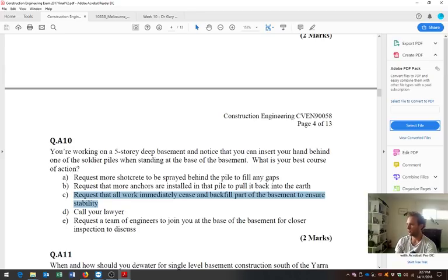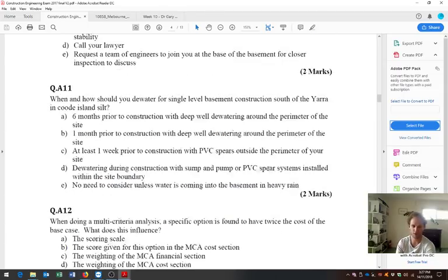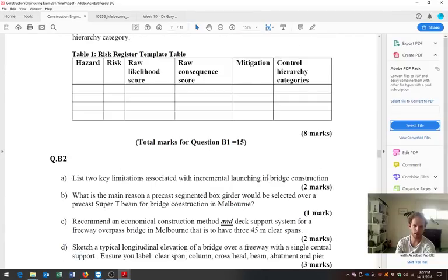2017 B2C. 3 spans, 45 metres. So plate girder is pretty good, but the best solution here is... Actually, let me double check this question before I get too far ahead. B2B. Sorry. So the best solution here is a composite steel box section. Jeff talked about them a bit in his lecture, but we've got a steel box section that's cast with a...